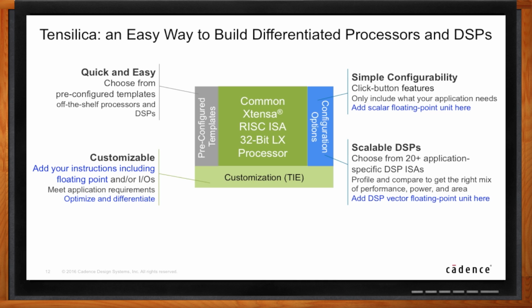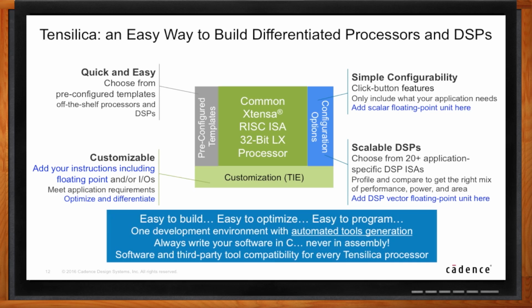Yeah. Well, actually, once you configure your DSP, the Tensilica processor generator gives you a development environment with automatically generated tools which actually match the DSP that you have just configured. So as a part of your processor generator, you also get the tools bundle, which includes the compilers, the development environment, the debuggers, which actually match the DSP that you just configured. So you can write your software using the tools that you got from the processor generator.